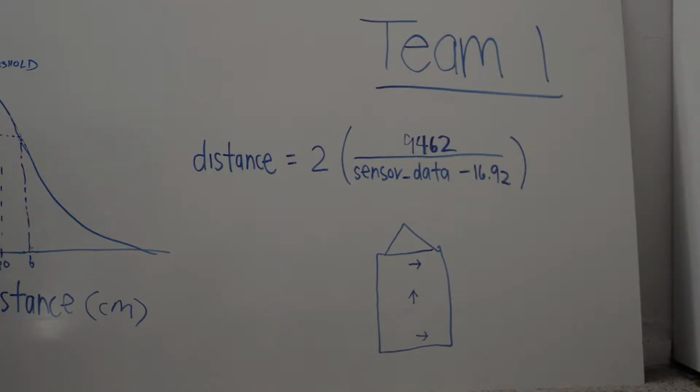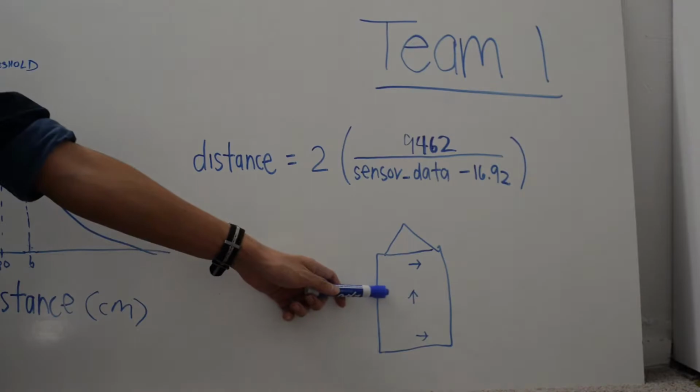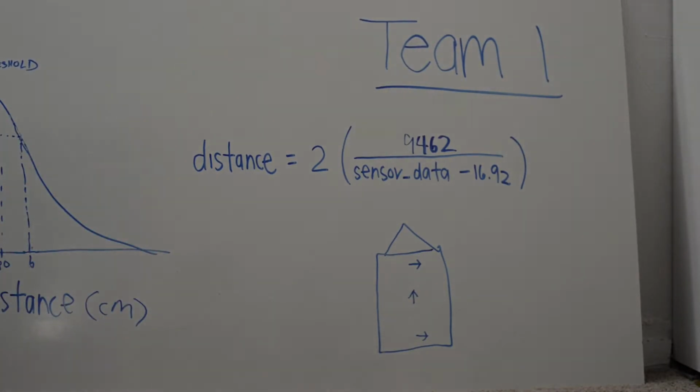For our rover, we chose to use 3 long-range infrared sensors. 2 are oriented facing right, and 1 is oriented facing front. The max range for these sensors is about 120 centimeters. The front sensor is used to detect walls directly in front of the rover, while the right sensors are used to wall correct, which will be explained later in the video. We chose to use infrared sensors because they do not have a conical range like the ultrasonic sensors, so there is a smaller range for error.